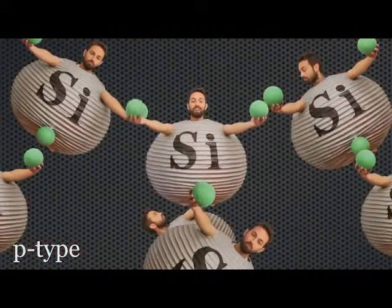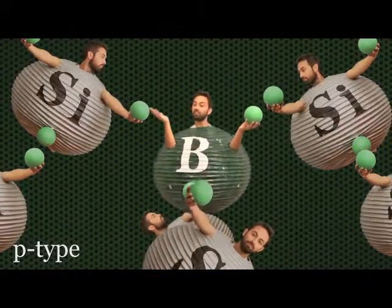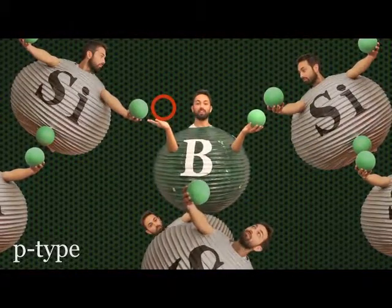In P-type doping, an element with only 3 valence electrons is added to the lattice, like boron. Now this creates a hole, a place where there should be an electron, but there isn't. But this still increases the conductivity of the semiconductor because electrons can move into it. Now, although it's the electrons that are moving, we like to talk about the holes moving around because there's far fewer of them. Now, since the hole is the lack of an electron, it actually acts as a positive charge. And this is why P-type semiconductor is actually called P-type. The P stands for positive. It's positive charges, these holes, which are moving and conducting the current.